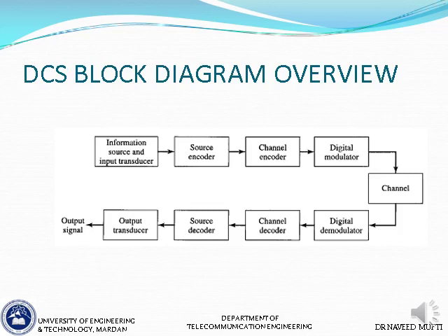Okay, so now I bring you back to the basic block diagram of a digital communication system. As you know, we have probably done every single block. So we started with our discussion that if the information is in some form other than electric form, then a transducer is used to convert it to an electrical signal, which is analog, and then if the signal is analog, it is first converted to a digital signal, and within analog to digital conversion there are 3 steps. There is sampling, there is quantization, and then there is encoding. And after encoding, we finally have the bits, and then the bits need to be represented by a waveform, and that's where the line coding comes in.